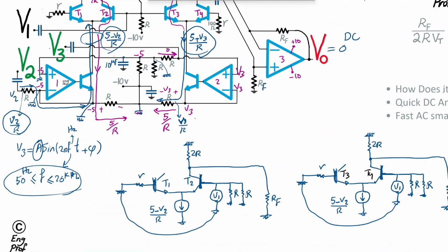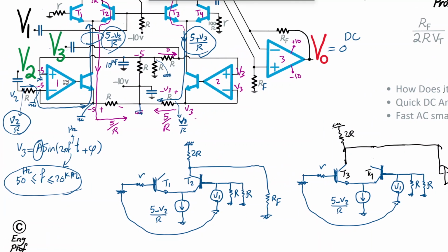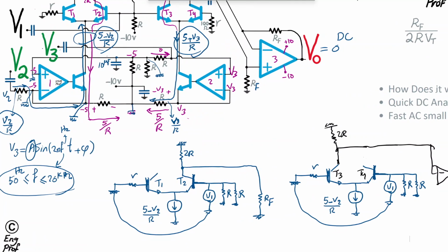And the connection is not like this. The connection is, so I don't care about T4 for the time being, but the connection is, we have connection to 2R resistor, again AC grounded, virtual ground, and then we go down, and then we have connection to the op amp at negative terminal, which is then going to its output with resistor RF. So we have that scheme.